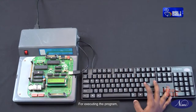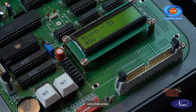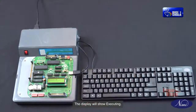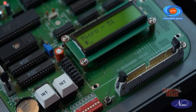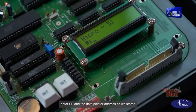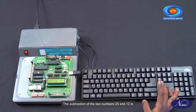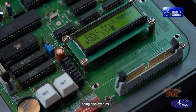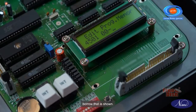For executing the program, enter Go, starting address, that is 4200, and click enter. The display will show executing. Now click on the reset button. For displaying the output, enter SP and the data pointer address as we stored the value in it. Here it is 4500 and click enter. The subtraction of the two numbers 25 and 12 is being displayed as 13. Hit the enter key to view the borrow. 00 is the borrow that is shown.